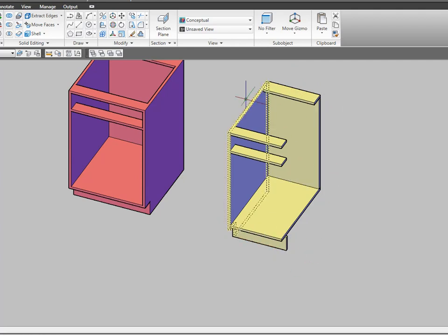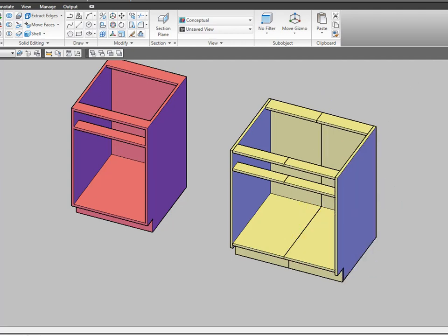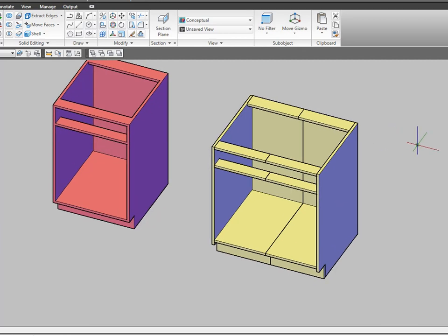3/4 wide. So all I need to do now is mirror this half cabinet to create a whole cabinet. And it asks me for 3 points. I selected 3D mirror, prompts me for 3 points, and now we have two half cabinets, 14 3/4 wide, totaling 29.5. And all you need to do now is join some of these parts, actually union them, the union command.